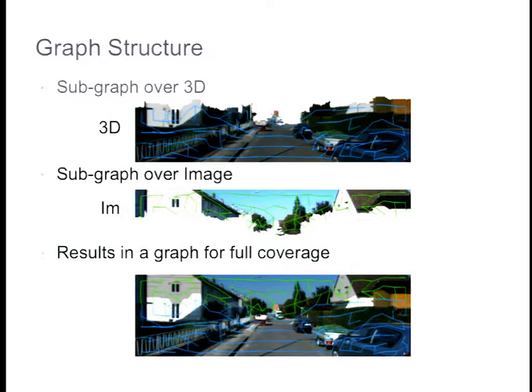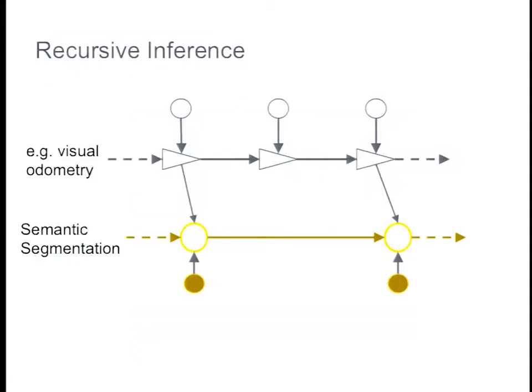All right, so this was the single view setting and how we can deal with multiple sensing modalities. So let's have a look at what we are going to do if we have to deal with videos. Given that our graph structure is set up in 3D, we are going to use a lot of the exciting work which has been done over the past decades in SLAM, where we can fairly reliably compute the pose between consecutive views using some simpler feature tracking techniques. So given the visual odometry pipeline, the pose between the views can be computed.